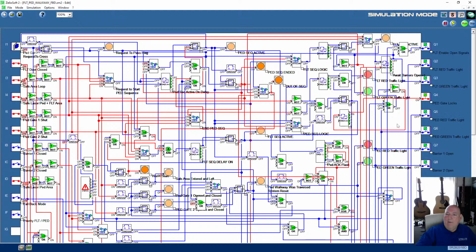If we get all red lights flashing, it means we're out of sequence. It needs a reset or a sequence crossing to acknowledge that. Right, so that's normal. We're out of sequence, so we need to give it a press here and a press off. It should initiate a sequence to cross the road. It has done, so it's recovered itself from being out of sequence.